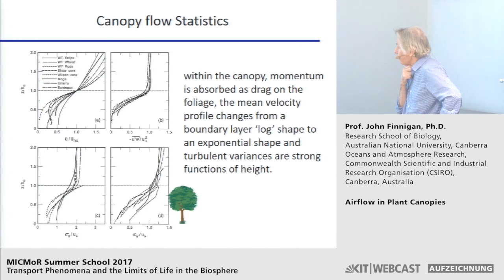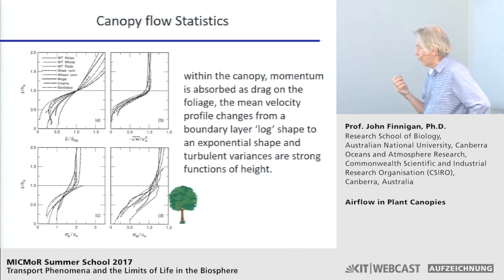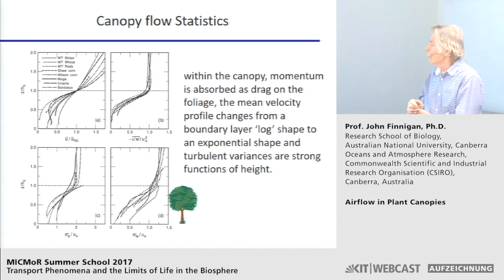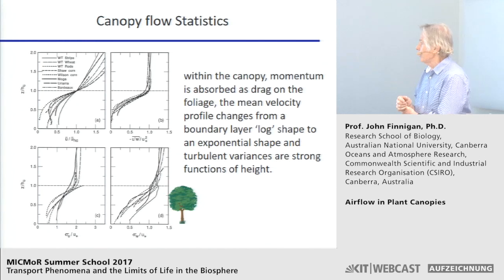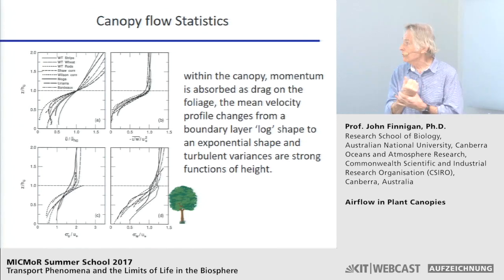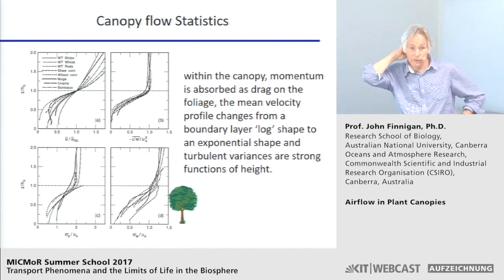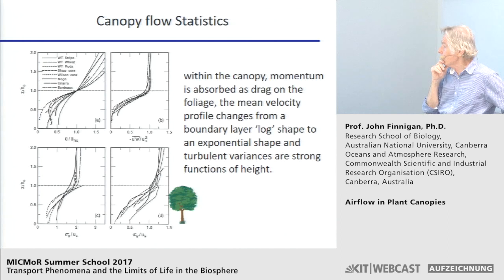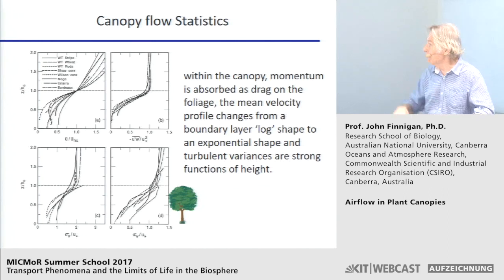So interestingly enough then, when we look at the way that canopy turbulence from many, many different canopies collapses, if we use either the vorticity thickness, which I'll explain later, or the canopy height, as in this set of pictures, as scaling values, and u star as the velocity scale, then we get an incredibly good collapse from canopies which vary from 25-meter pine trees to some deciduous trees to wind tunnel models that high, and basically everything in between.